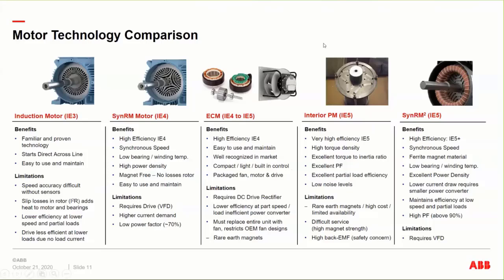And then you have true permanent magnet motors. These are great designs, but they're typically not cost effective at lower horsepowers, where you're seeing up to these 15 kW or 20 horsepower ratings. PM motors really only shine once you get above that because they use rare earth magnet materials. They're a lot more expensive, more cost in them, difficult to service.